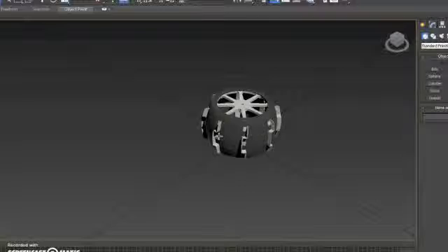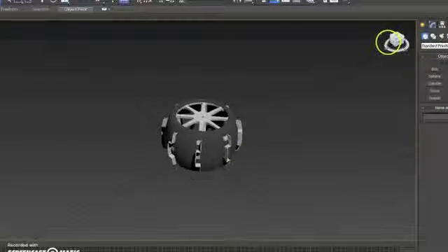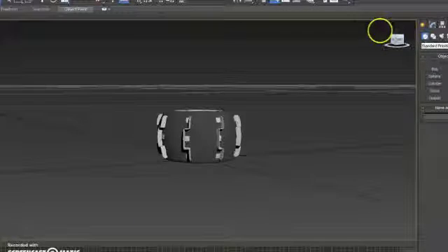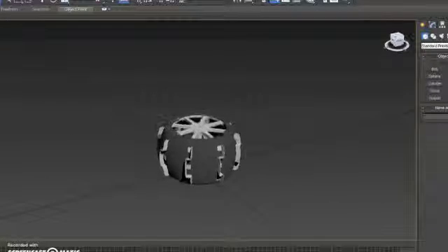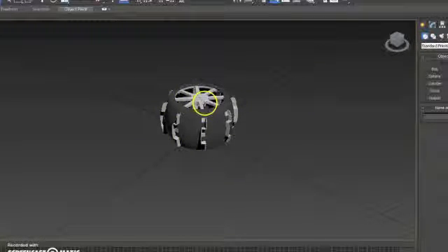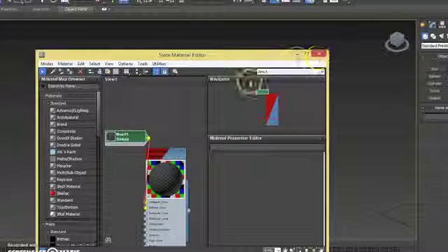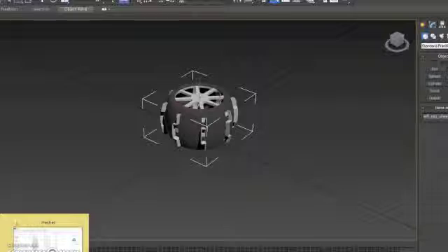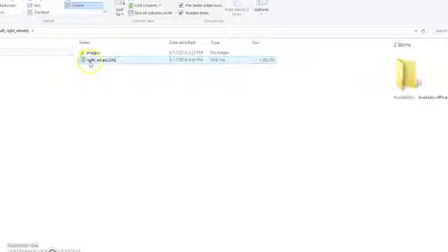Let's look at an example of that. So here we have a wheel that we textured. To do this, we want to include the grousers just for aesthetics. So we did the similar export process, except the grousers were not suppressed, and this created that STL in the same orientation as the previous export. And we took that STL and textured it. As we can see, we applied a small bitmap to this face. Then this part can be exported as a Collada file. Be sure to include the image in your Collada file. So we can export as Collada, and then we have our DAE and the associated image, and then we can include that in the visual mesh description.